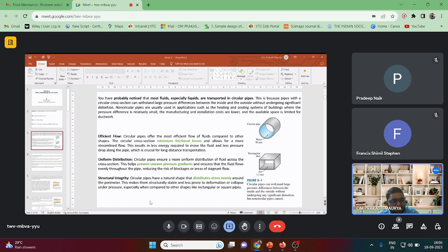The reason is that the repeating variables should appear in pi 1, pi 2, and pi 3, and when you merge all the pi terms into the final dimensionless pi, it will be more applicable. So we select the three fundamental families: mass, length, and time.